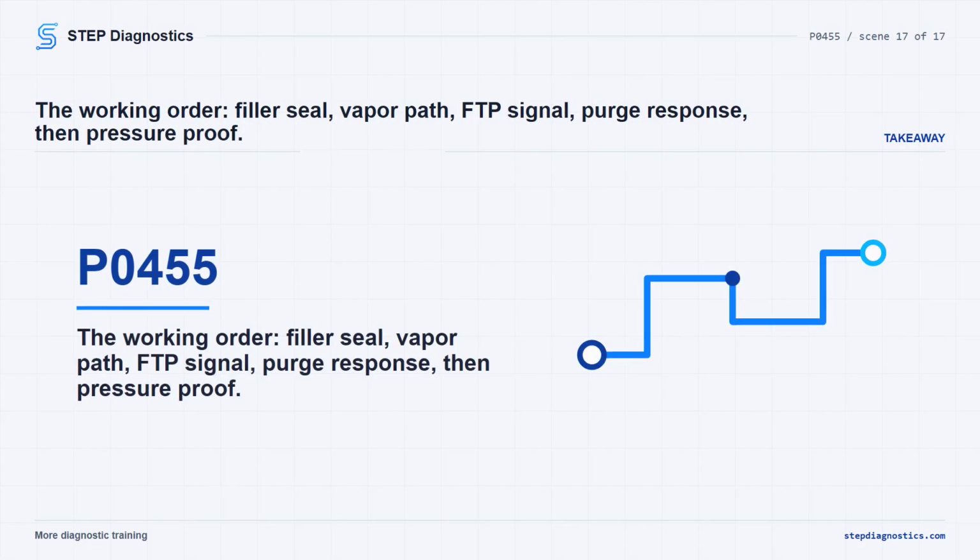If the purge valve passes, the test passed and no concerns are present, clear the PCM DTCs and repeat the self-test. If it does not pass, install a new EVAP canister purge valve, run the EVAP system test, clear the PCM DTCs, and repeat the self-test.